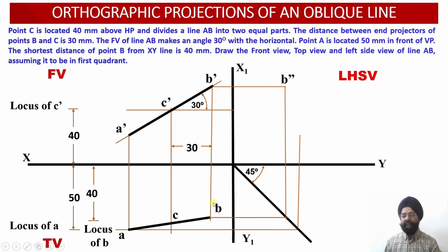So this is the point B projection. From point B, we have drawn this horizontal projector till it intersects with the transfer line, and from here we have drawn a vertical projector in the upward direction and extended this projector till it intersects with the horizontal projector line which has been drawn through the front view point B dash over here. So B double dash point has been located.